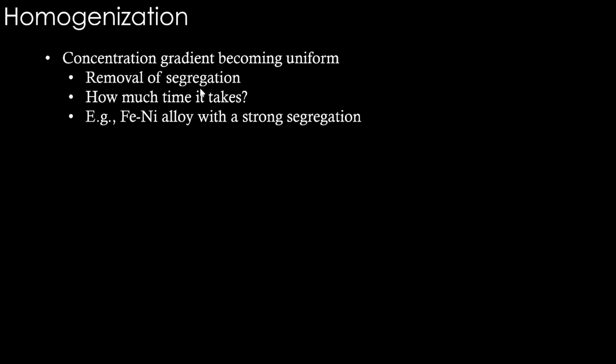And after homogenization, it is taken for any other processing, let's say sheet metal making or bar making, things like that. So all those processing will follow only after homogenization. Otherwise, the processing will be difficult. The material will deform in a very non-uniform way. All those problems will come. So it is important to do the homogenization. Therefore, how much time it takes is an important question to ask. This is directly related to productivity.